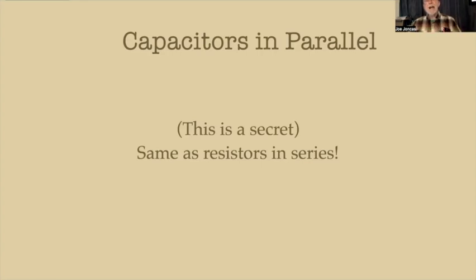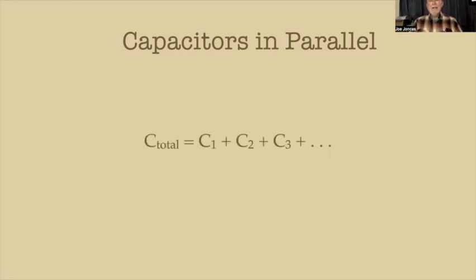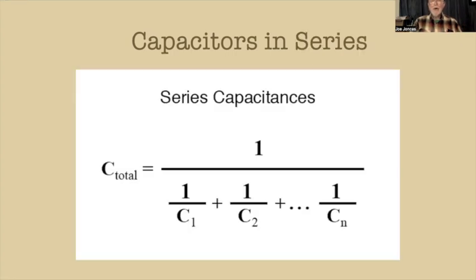That's 80 microfarad. It's that simple. Just C1 plus C2 plus C3, however many you put in parallel, you just add them all up. You might have a 220 microfarad electrolytic and then put a 0.001 microfarad capacitor in parallel with it. Won't make any difference except for when it will pass. But that's a whole other story.